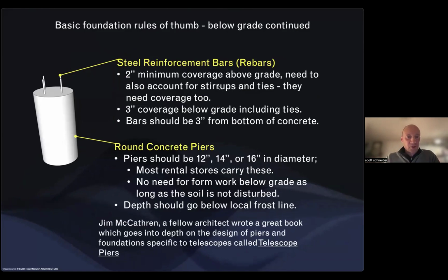And for piers, the same rules apply for coverage: 2 inches above ground and 3 inches below ground. And when you get to the bottom of the pier, you try to keep your steel rebar up about 3 inches above the bottom of the pier.